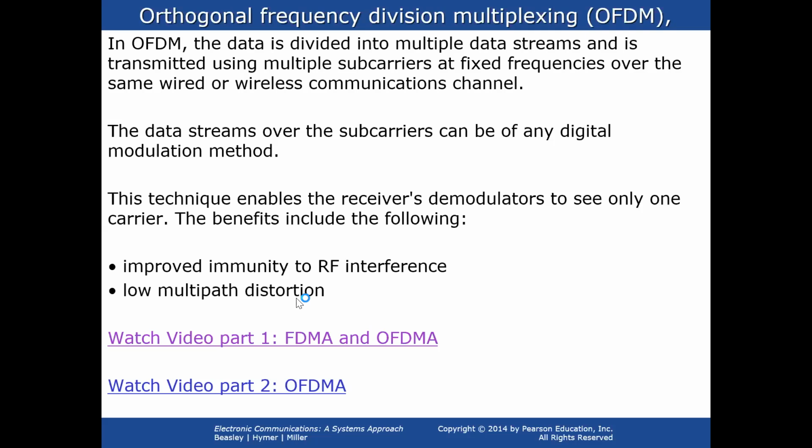Hi everyone, welcome back to the world of 4G. Previously we have shown how mobility and global connectivity was achieved by introduction of wireless communication. But there are several complexities associated with wireless channels. Multipath fading. Unlike a wired channel, which uses a fixed path, the signals in a wireless channel can reach a user using multiple paths. All these signals, known as multipath components, may have different channel gain and time delay. This combined effect causes what we know as multipath fading.